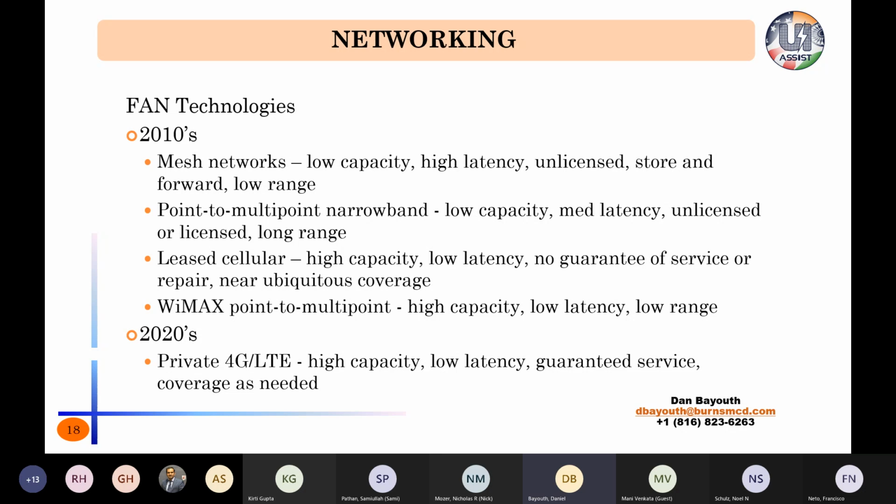So as we need more real-time visibility into the grid, the mesh networks don't scale very well, because really to get capacity in a mesh, I have to go add takeout points into the mesh out in the middle to reduce the number of hops things have to go. Now I effectively cannot increase channel size. The frequencies these use are unlicensed. I'm restricted in how I'm allowed to use the RF frequencies for mesh networks. And by and large, there is a reason your cell phone is not on a mesh network. The architecture just doesn't really scale and perform the way it needs to.